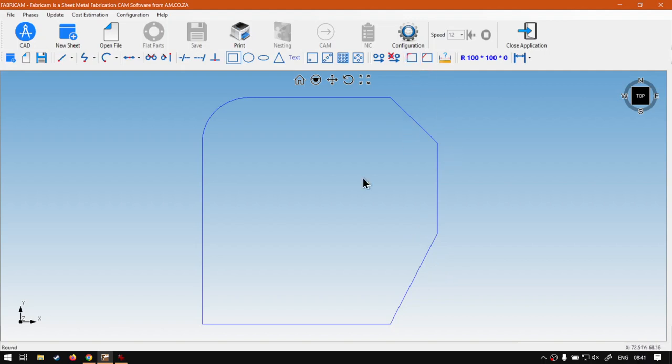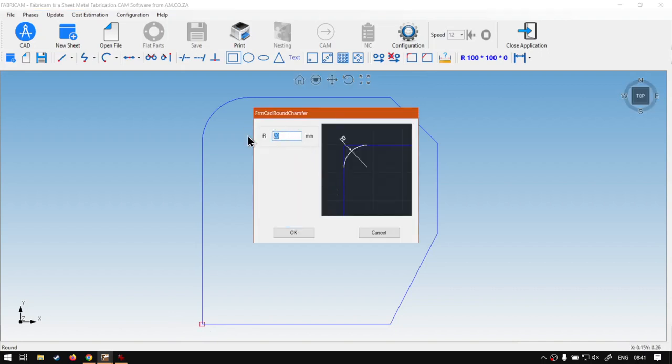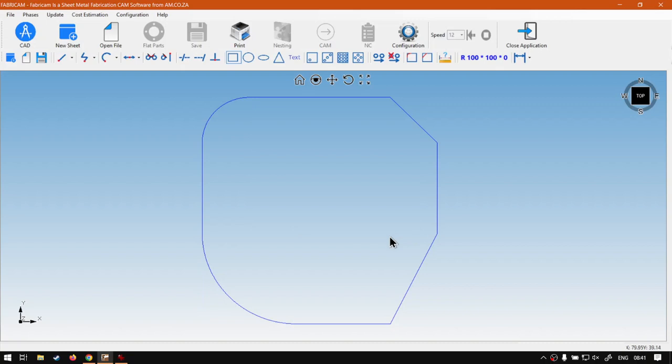And then let's just add one more rounding on the bottom. And then let's maybe make this one a bit more extreme. Go also about 40. You got a bigger rounding there. So like I said, a handy tool. You'll probably use it a lot with products where you'll either use a rounding for the corners or chamfering, but that'll depend on your final product. But yeah, otherwise that is it on the rounding and chamfering.